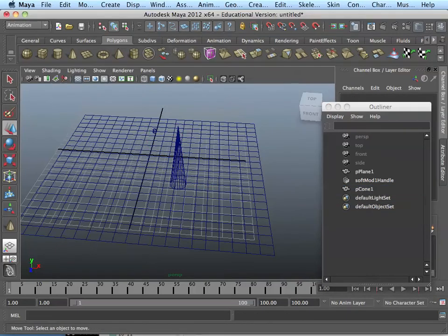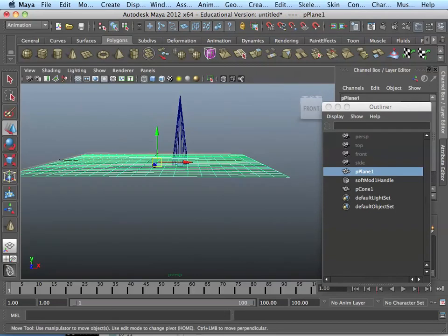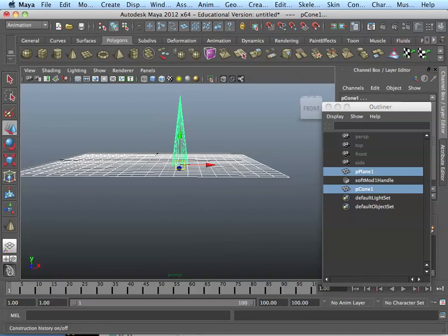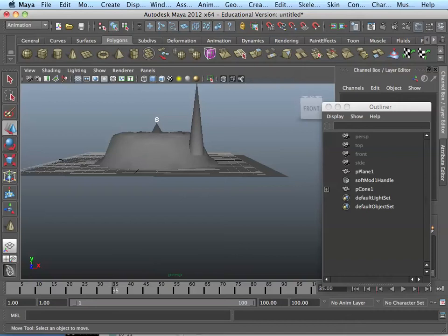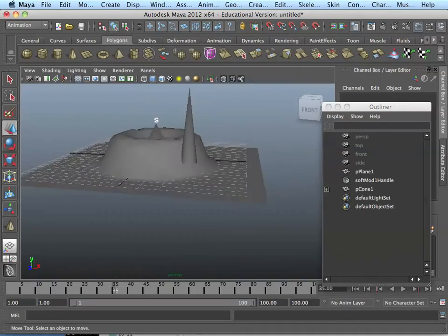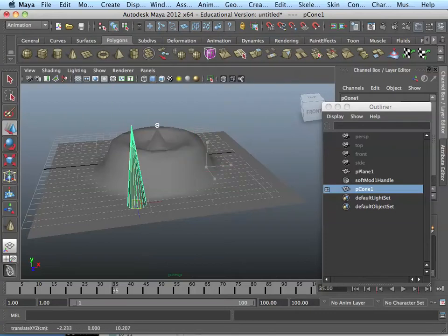All right, so now I'm going to go back, pick the surface, pick the cone, and say geometry. And as I move, right, it's really simple. The geometry constraint only controls translate. It doesn't control anything about rotation. But now I can only move this cone on the geometry.